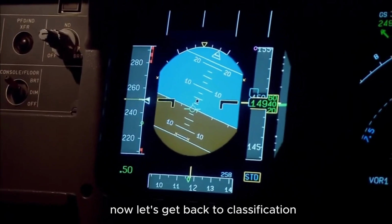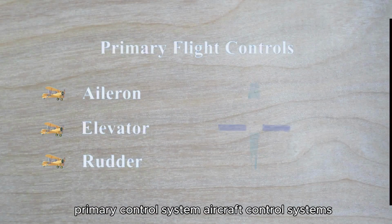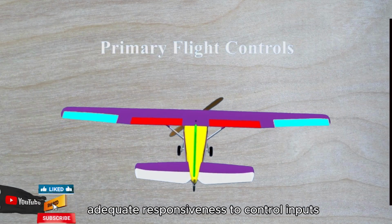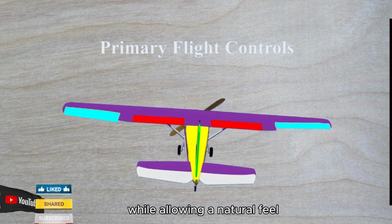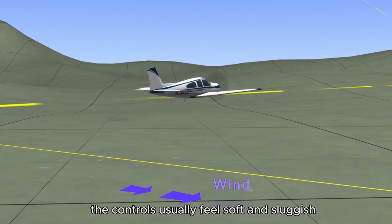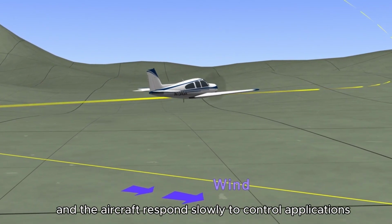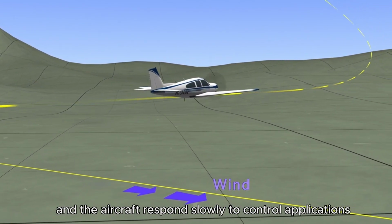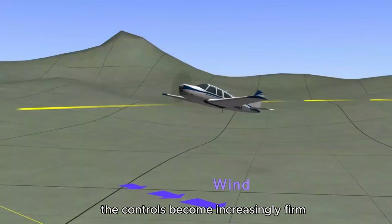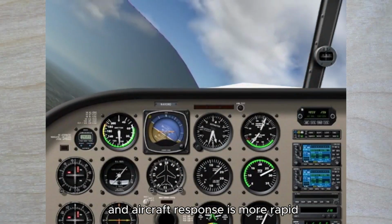Now, let's get back to classification. Primary control system. Aircraft control systems are carefully designed to provide adequate responsiveness to control inputs while allowing a natural feel. At low airspeeds, the controls usually feel soft and sluggish, and the aircraft responds slowly to control applications. At higher airspeeds, the controls become increasingly firm and aircraft response is more rapid.